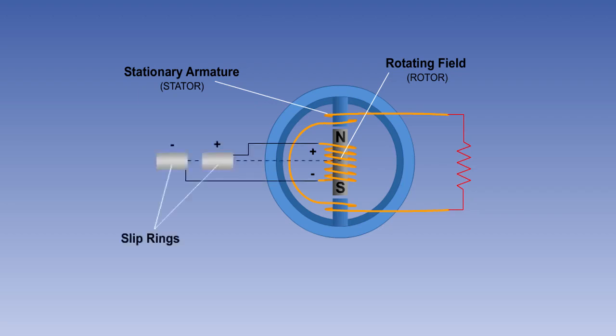One advantage of a rotating field AC generator is that only a low current is fed through slip rings to the field windings. The output is taken from the stationary armature windings, which means that problems associated with arcing from the brush gear are greatly reduced. The stator windings or coils are directly opposite each other and are connected in series to supply the output. The rotor consists of two poles of opposite polarity.